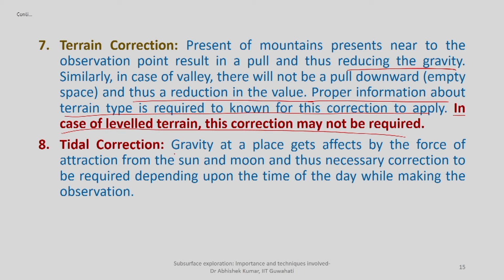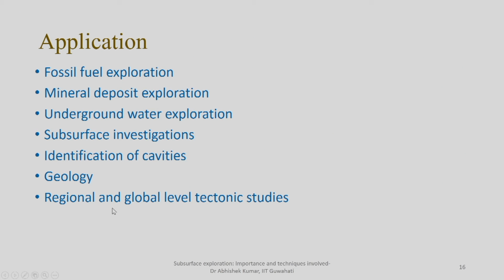So, tidal corrections: gravity at a particular site is affected by the force of attraction from the sun as well as the moon, and thus a correction is required depending upon the time of the day. So, these are the corrections. Now, before going to solve any numerical problem, let us discuss this gravity survey.